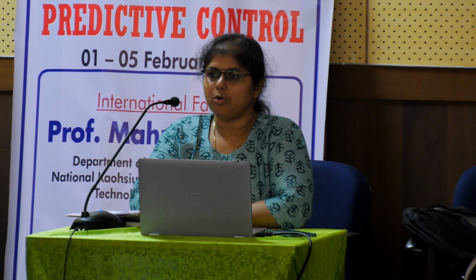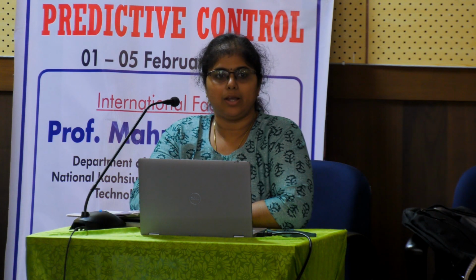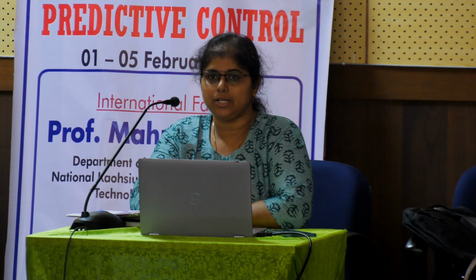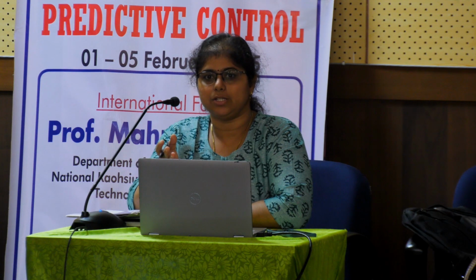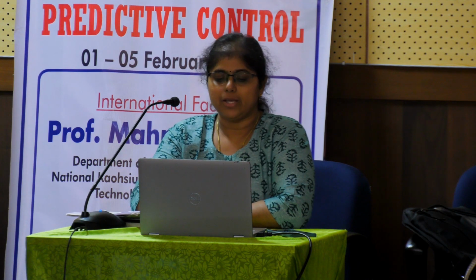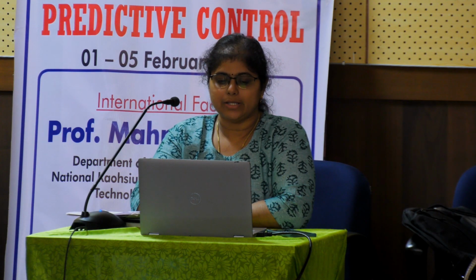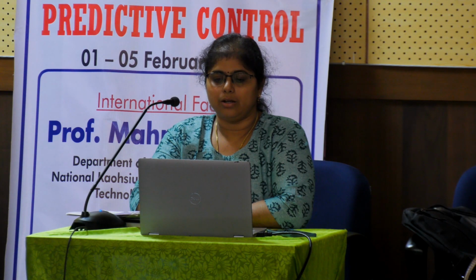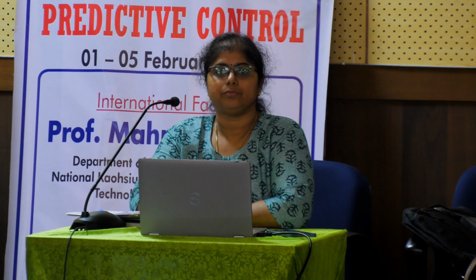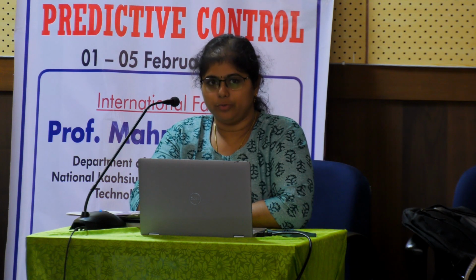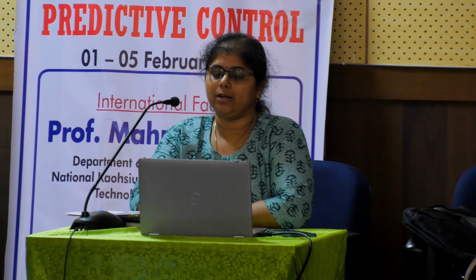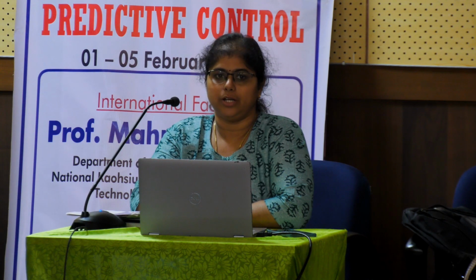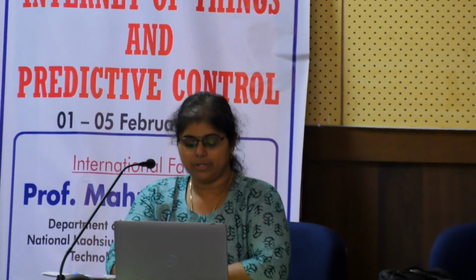Any state space model is x dot of t equals Ax plus Bu, and y of t equals Cx plus Du, where x is the state of the system, and x dot is the future state of the system that we are trying to predict based on the current state, x of t. u is the input, y is the output, and A, B, C, D are the matrices connecting the input and output. So this is the state space representation.